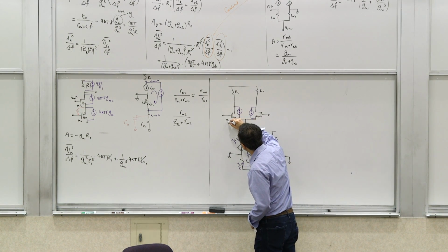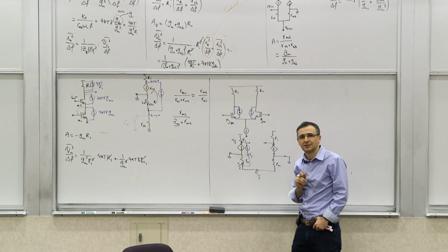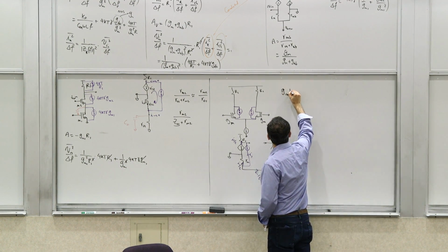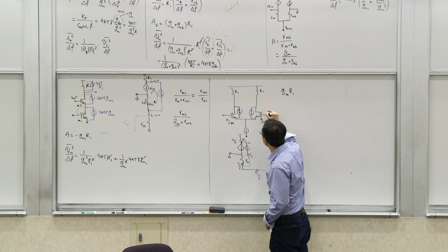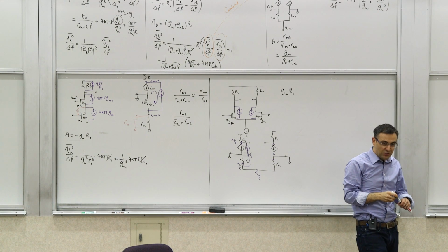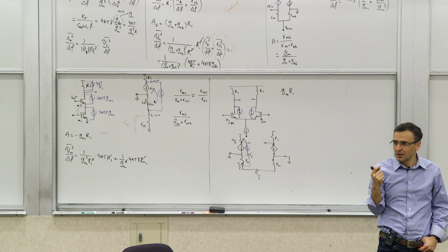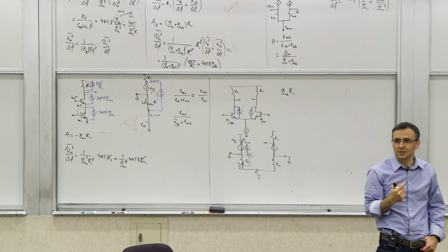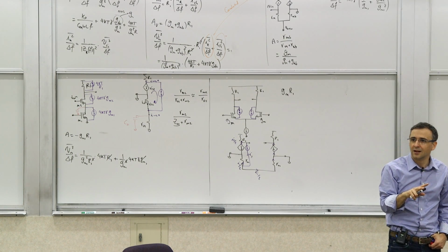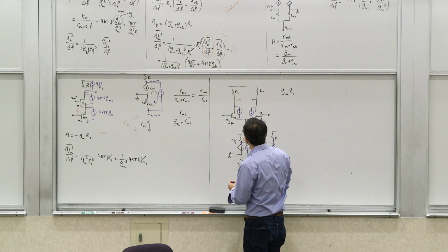If each one of them has a gm, the differential gain. So let's say each one of them has a transconductance gm. gm R1, right? So gm R1 is the total gain from this differential input to this differential output, which is the same as the gain of a single common source. But you have now two noise sources. Each one of the noise sources that you had one of, now you have two of, right? Because you have these two that are uncorrelated. And if you look at the noise sources of these two, they are going to be uncorrelated too, right?